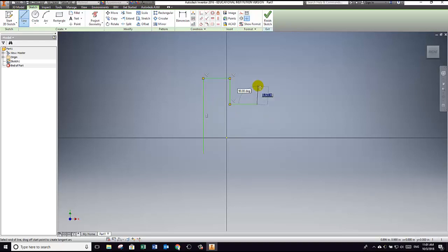I'm going to go a little bit faster because these steps are all the same and the distances are all the same, 0.75, 0.75, until we get to right here. At this step, we have to go down 2 cubes, which is approximately 1.5. Notice all of my distances have been approximate. That's because when we sketch this, we don't try to be perfect. We just try to get close, and then we'll make it perfect with our measurements after we've created the outline or the profile. So all I'm really making sure I do is that I get everything horizontal or vertical.